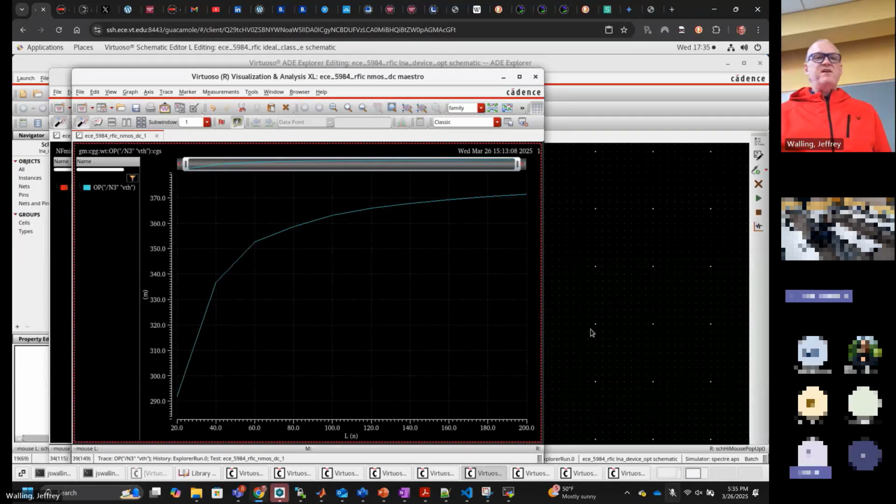It used to be that in short channel bulk CMOS, in order to get the devices to work the way they want, they dope all around the device, and all those dopants cause all kinds of stresses on the device. The effect of those stresses reduces as you increase the length of the device, and that was what was causing it.